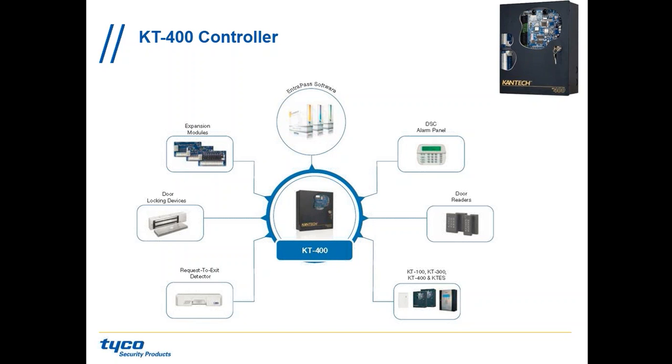We had a project in Barbados, and they had a data center. They actually need 3 doors. They have 3 doors they need on the access control, but they needed 160 something input supervised, because they have cabinet, they have rack, anything the customer wants. If they open, I think, a window, they want to know. If they open a drawer, they want to know. Now, this integrator was planning to use KT300, and each KT300 with input board can go 16 input, etc., etc.